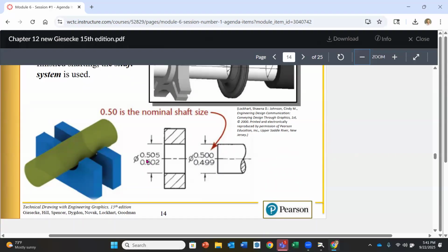And in this case, you might have a couple of things that you could do. You could either bore it out, like on a CNC machine, and then it would just interpolate and make that hole size. Or you might have to have a special tool made in order to create that. Okay, which isn't the end of the world if this is what's required. I don't want you to go away from things, but I also want you to understand that you don't want to be specifying a hole diameter like this unless there's a reason for it on the shaft side.